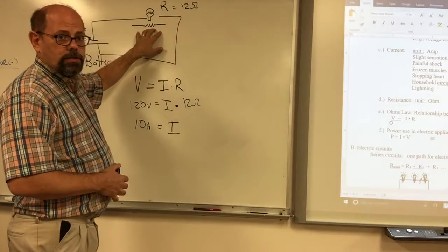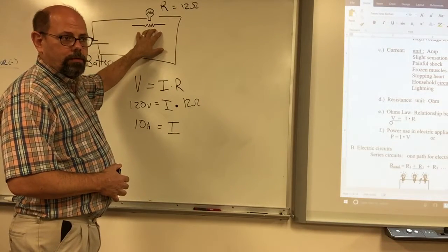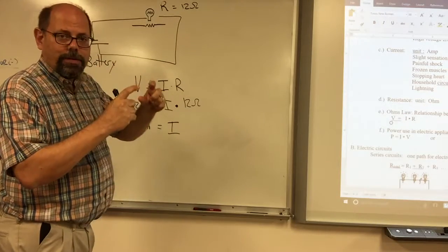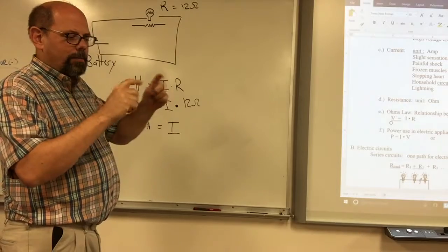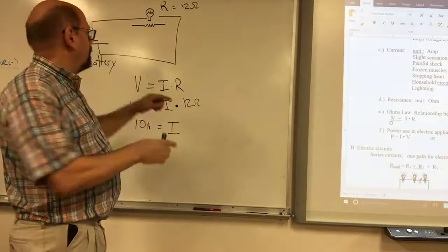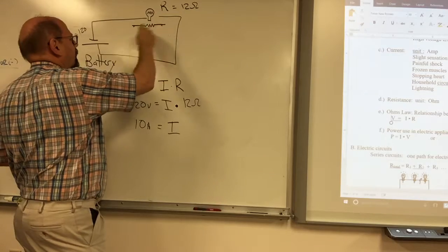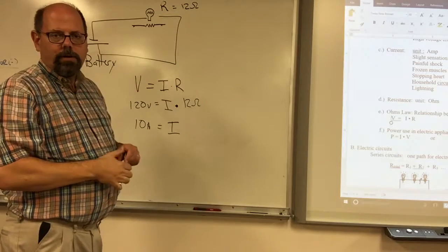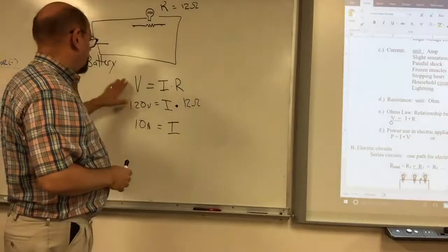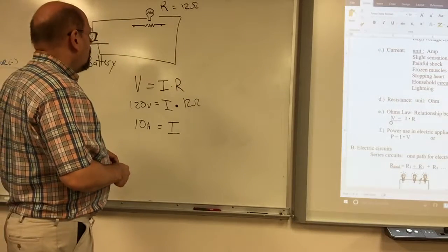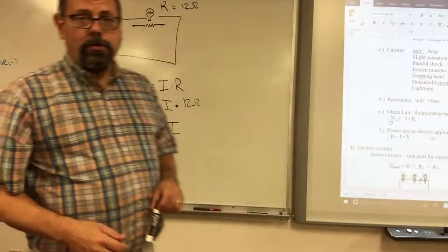The resistance is usually measured by a multimeter or an ohm meter or resistance meter. Radio Shack sells those if the Radio Shack's still around. So Amazon must sell those. And they'll come up with a little number at the top. And you'll have to test these by actually putting a probe on the wire here and here. And it can sense the voltage drop across here. Okay? That's how these get determined, each of these values. So, good. That's the way you're going to do these problems.